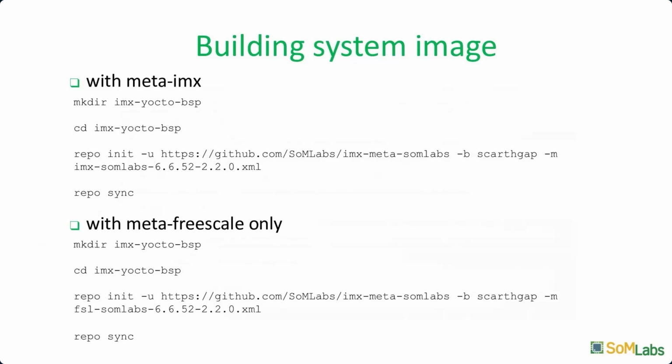So depending on needs, again, you need to choose the proper compilation command, and the compilation process is quite simple. When you have the local workspace directory, you need to initialize the repository itself. The repo init manages the GitHub repositories and downloads the Yocto sources that I described before.